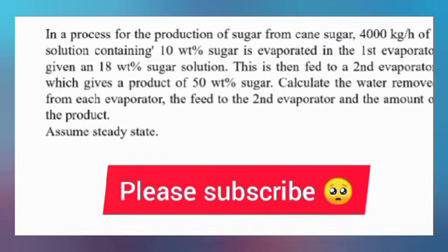In a process for the production of sugar from cane sugar, 4,000 kilogram per hour of solution containing 10% by weight sugar is evaporated in the first evaporator, giving an 18% by weight sugar solution. This is then fed into a second evaporator, which gives a product of 50% by weight sugar. Calculate the water removed from each evaporator, the feed to the second evaporator, and the amount of the product, assuming steady state. Let me take the question again.